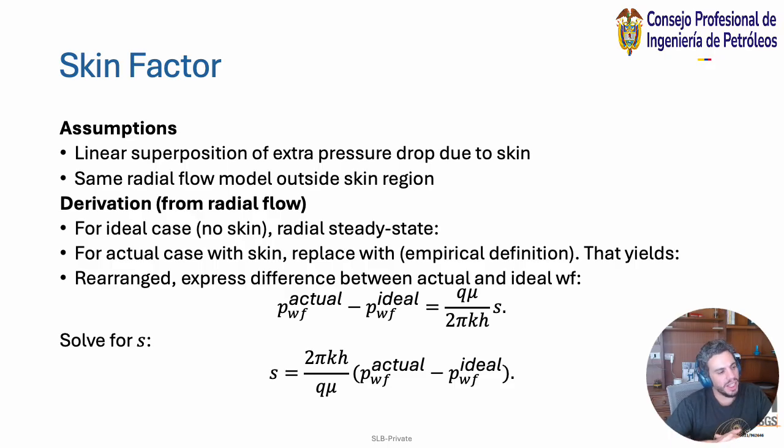And there are guidelines on what we can consider to be extremely bad. If you see a skin factor of +5, you can cut your production by almost half. A skin factor of -3 means you can double your production rate. That's almost equivalent to what we're talking about with acidization. That's what we should see as we're doing that, right? So that's something to take into play, right?